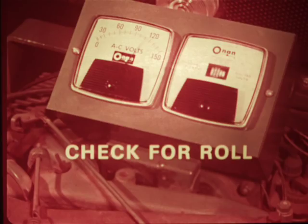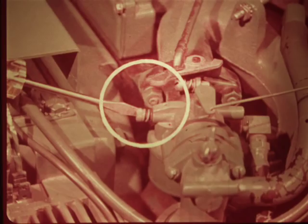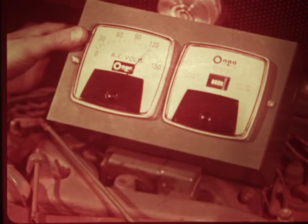Then, with the no-load speed set, check the engine for rolling or hunting or an unsteady meter reading. If there is a roll, adjust it out by turning the idle mixture screw on top of the carburetor in or out until the engine runs smoothly. Then check the frequency for proper no-load RPM after setting the idle mixture screw.